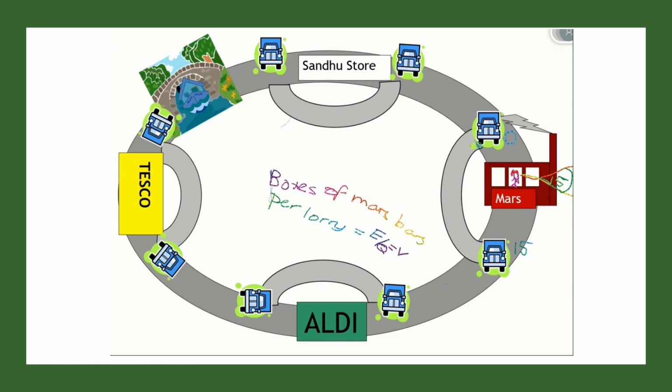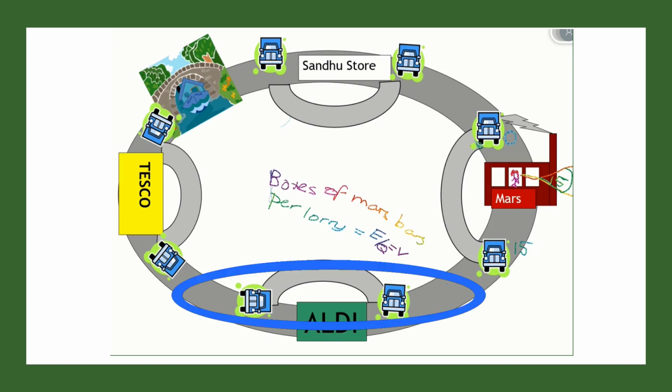Now, can you stand at the side of the road and count the number of Mars bars on the lorry? No, you can't. And that's the same with voltage. With voltage, you can't put a meter in the circuit and expect to count the voltage across it. What you've got to do is sample. That's like the weigh bridges, if any of you have seen them, where the police sometimes make blockades along the motorway, pull some of the lorries off, weigh them, and check what's inside. And that's what's happening here. That's why, when you connect a voltmeter up, you put it across the component.